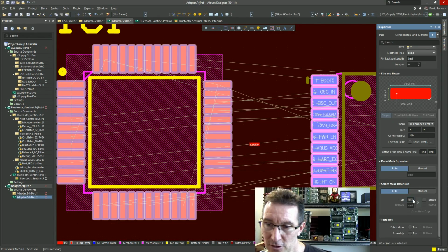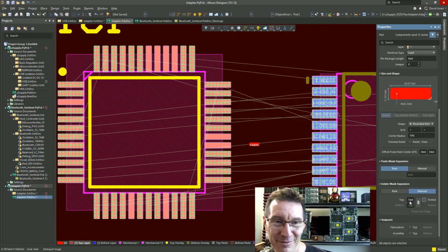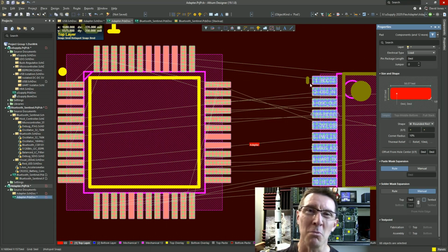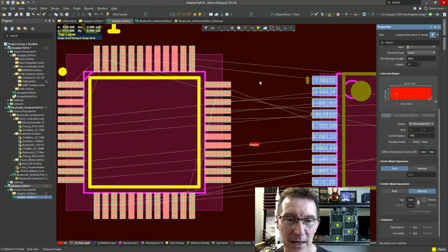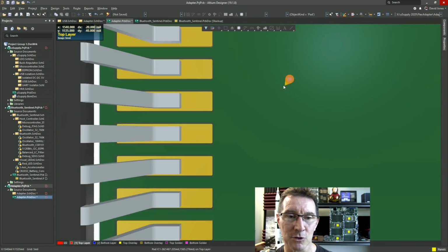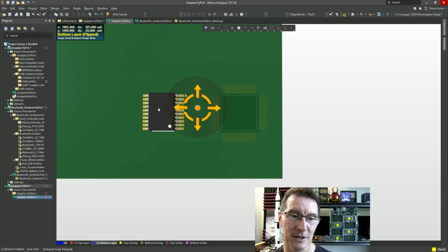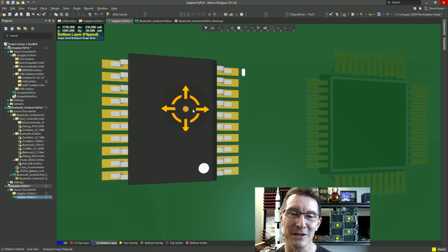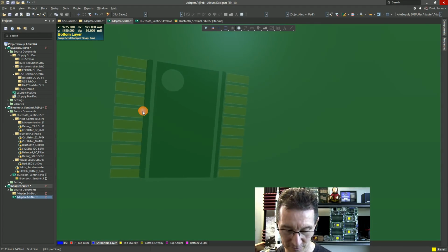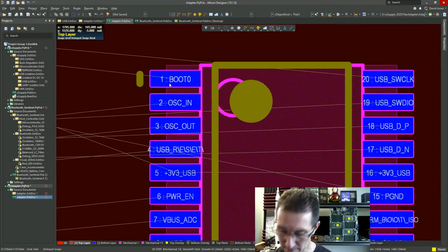Solder mask expansion, 4 mil. So we'll change that. That's coming from the rules. We could have changed the rules, but who cares? Doesn't matter. We're not worried about this. There we go, 1 thou solder mask expansion. That'll do it. Now, if we go in here like this, bloody error markers. There we go. We've got solder mask between our pads now. It's a Christmas miracle. So we can flip that over and you can see there's a chippy there. But of course there won't be a chippy because that will just have pads. Anyway, what we want now is to go in and put some manual vias.